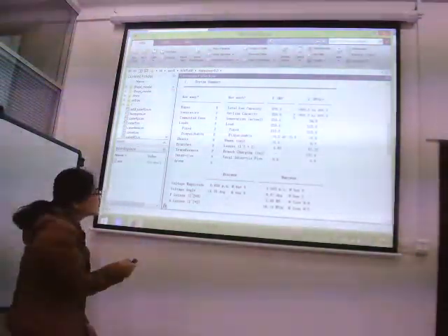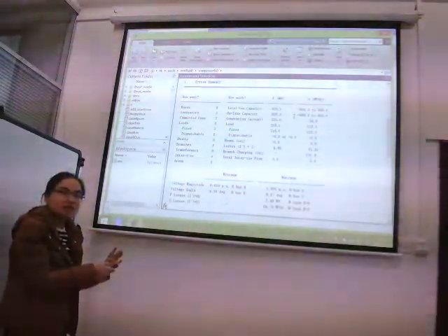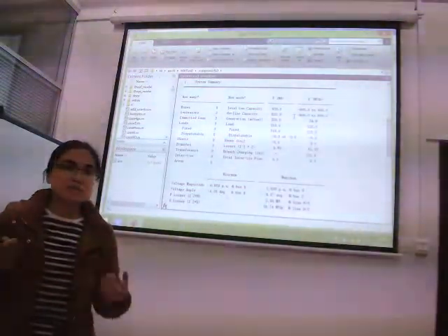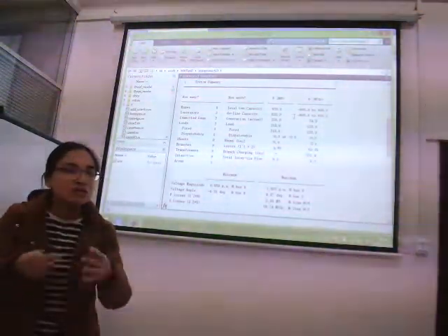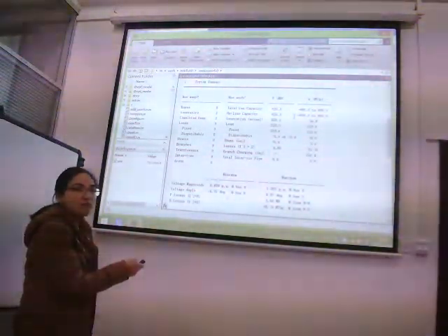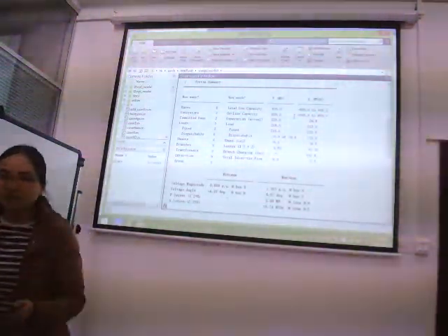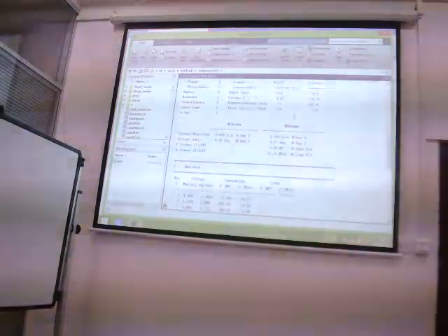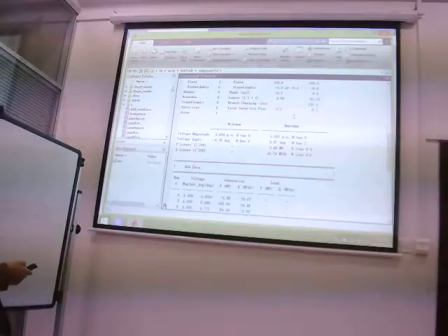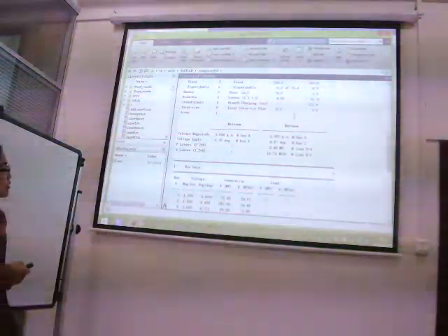We have to focus on the power system losses, because the losses are the key for us to determine whether the system is economic or efficient at transferring power flow. The losses here are 4.95 megawatts for this system. Now this is the voltage magnitude for the system. For the 9-bus system, the maximum voltage magnitude is 1.003 per unit, and the minimum value is 0.958.